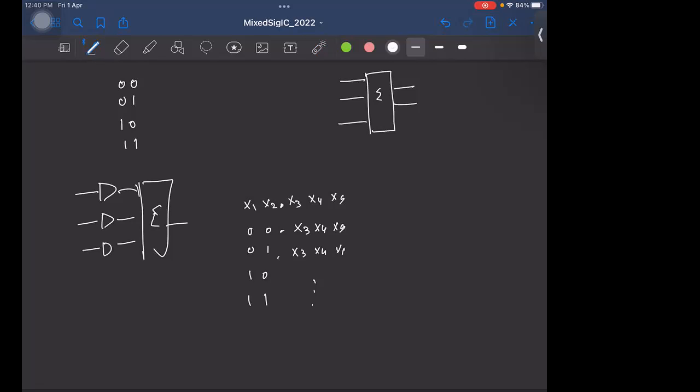No, the point is alpha. It depends on how much you want to match alpha 1 to alpha 3, right? See, ideally, the exact value of alpha 1 can be, let's say, 0.0005 or something. It depends on how accurately you want to match in digital, right? I can say this is approximately 0.004, or I can have one more bit and go to this order. So the more bits you allocate, the more closely you will match the actual alpha 1, alpha 2, alpha 3. And of course, you can't exactly cancel it. All you do is try to minimize it. That's all.